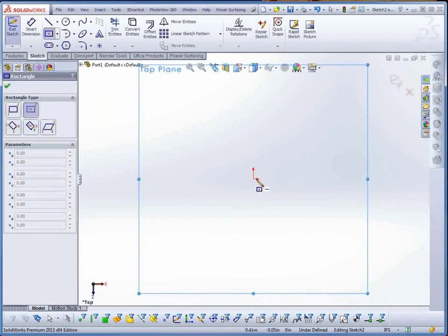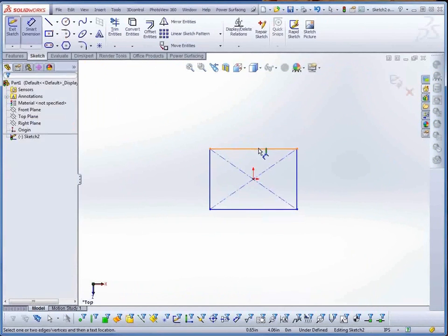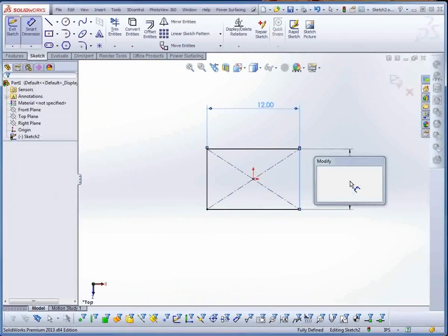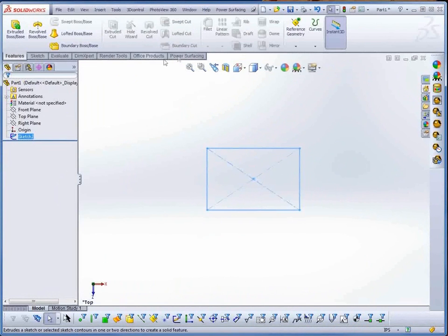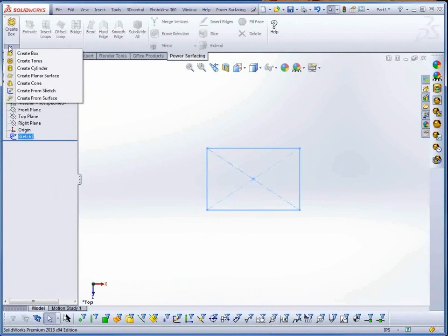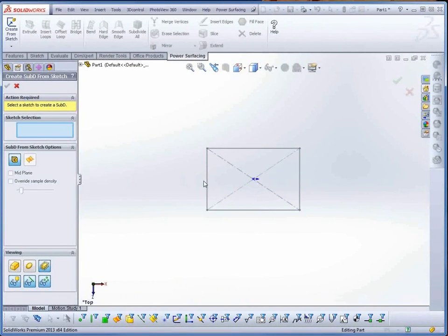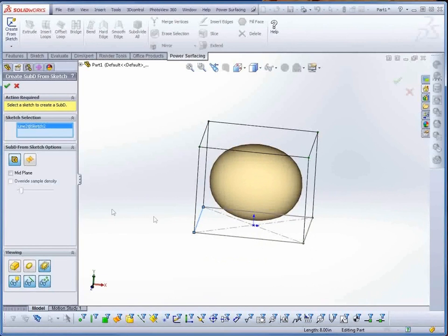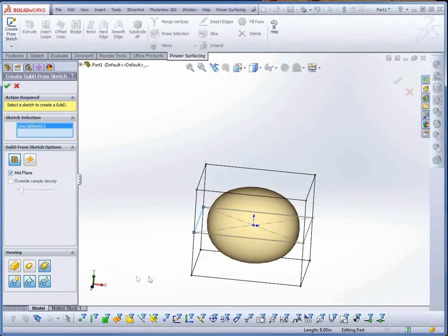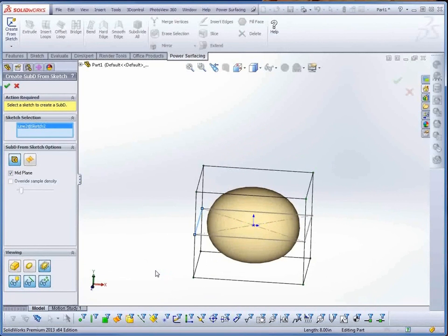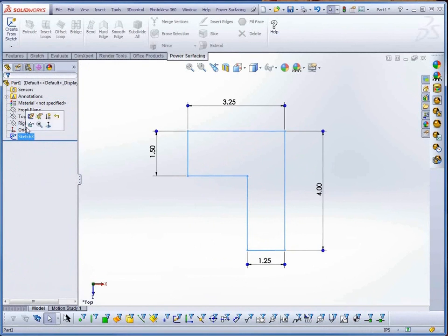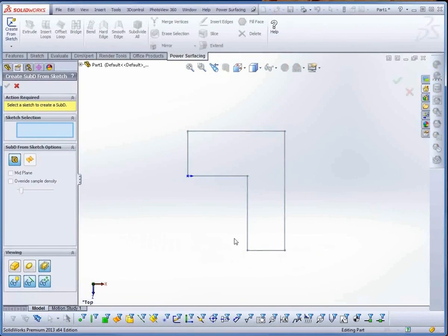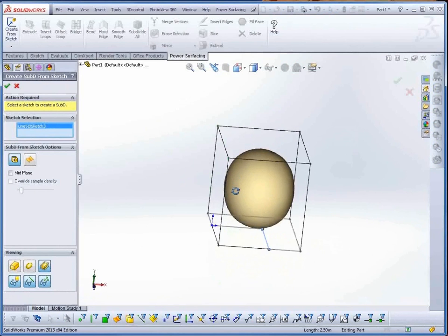A third way to start your Sub D is with the sketch. This allows you to start with a predefined location and orientation. With Create from Sketch, you have two options. As a solid, the sketch can be extruded up from its construction plane, or both directions from mid-plane. For solids, sketches over 4 sides will use only the bounding box, so keep it simple.